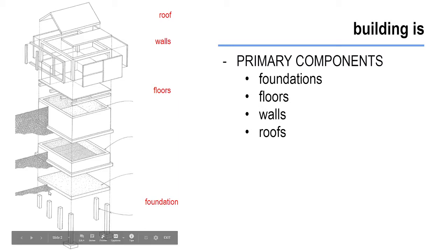The first thing we need to remember is that we can break our building down into four main construction systems, or four main components. The foundation, which we discussed last class, its purpose is to evenly distribute the load of the building throughout the soil so no damage can take place. We often would damp proof it to keep water damage from happening and seal off the foundation, because especially with the materials we tend to use for foundations, water can seep through those walls through capillary action.